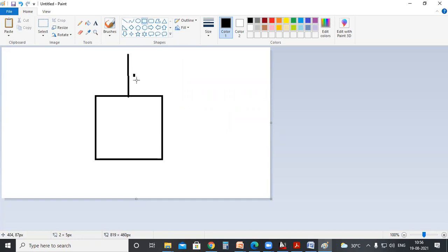Here we will provide the surge protective device in parallel connection, and this one will be earth. Whenever there is incoming surge current, this will detect it and bypass the surge current safely. This surge protective device will have some cartridges inside the equipment.